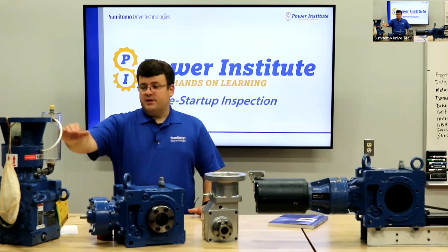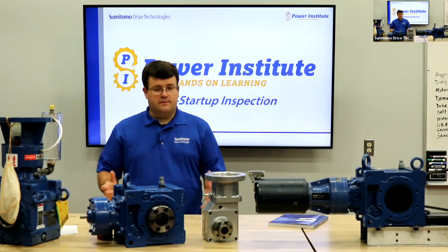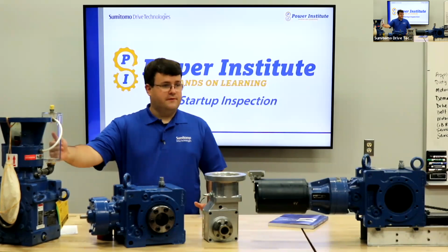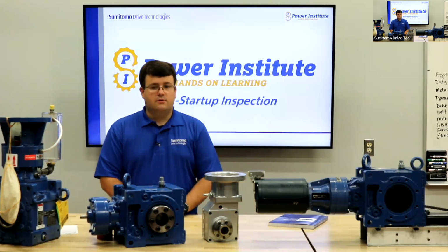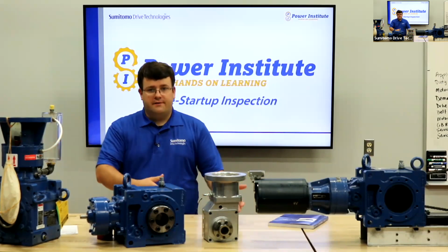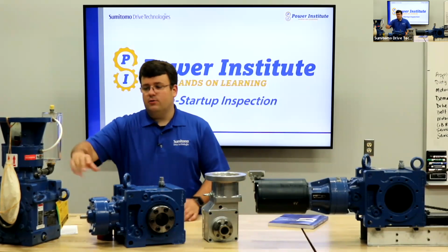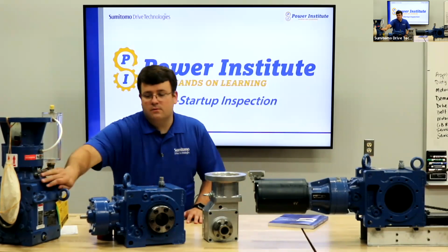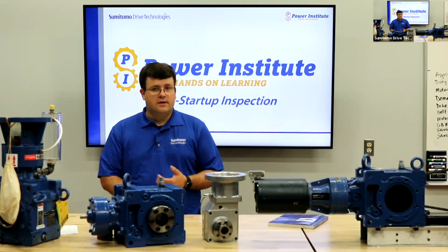From there, you want to check the oil level or if it came with oil. Some reducers, depending on the company, don't come pre-filled. If it's going to a low temperature application or they want to use special oil, they won't come filled, so you'll have to fill it up. You want to fill it up to the correct marks. These will be marked here, or some places there'll be a bullseye gauge somewhere along the middle. You want to make sure you fill it with not only the correct quantity of oil, but the correct type of oil.